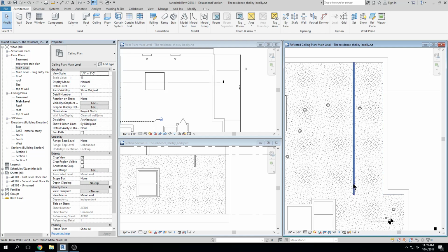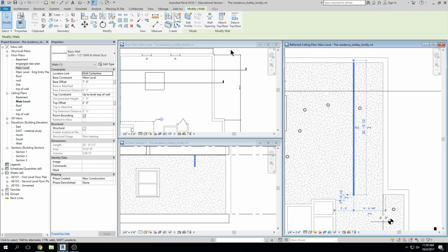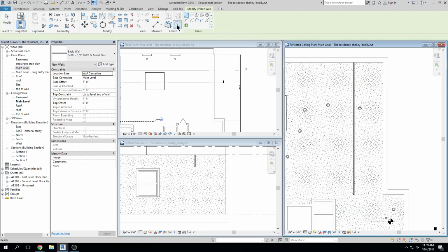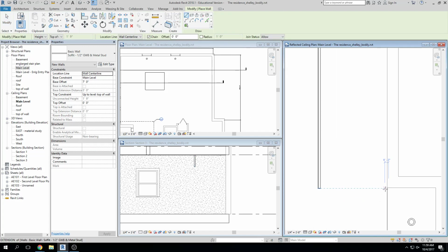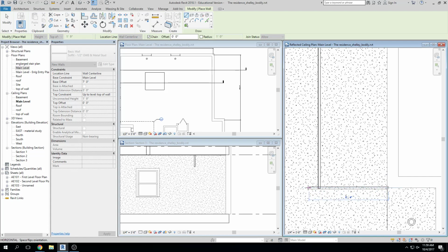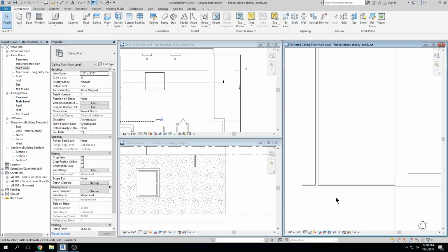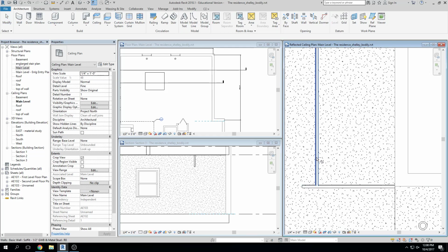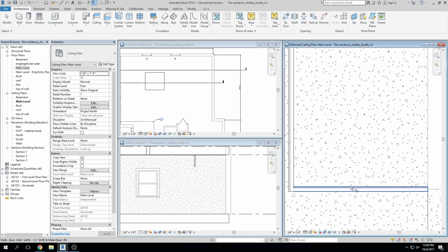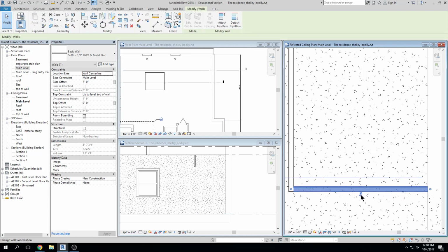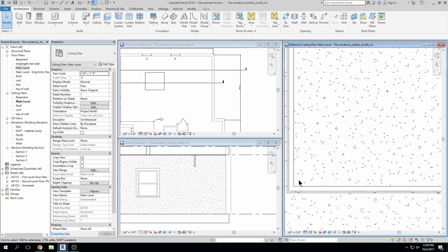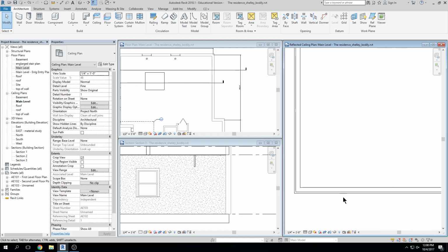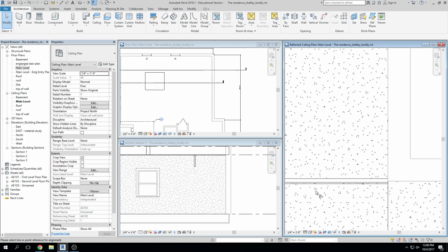Okay. I need to also probably do another little area right here, another soffit wall here to finish that off. So instead of going to wall again and creating all those same definitions, I'm going to click on this wall. I'm going to hit create similar. And I went a little too far right. TR, trim, click, click. Oops, the drywall's on the wrong side. Click, change it. You notice there's only drywall on one side for this wall type. AL, align, click, click.